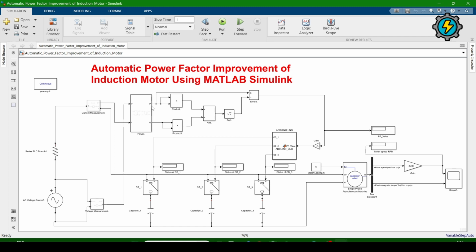In this, first we will multiply the active power to make it a square, and then make the reactive power a square. After making both squares, we will add both, and then we will take a square root. Then the answer will be the apparent power.